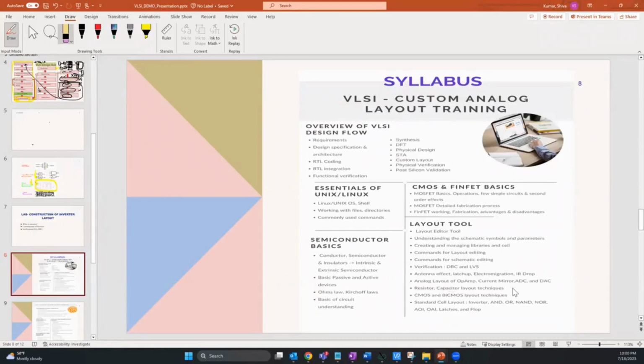But in analog layout, you need to maintain a lot of constraints like electro migration, latch up, antenna, and all these things you need to take care of. And a few more concepts will come, shielding and some other concepts. We will be covering those complete concepts in your training sessions. And later we'll have something called advanced layout concepts. We will be checking what the failure mechanisms, noises and couplings are, and full chip construction. And we'll be explaining how this IC will be integrated in the full chip.